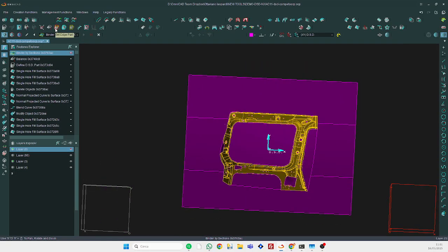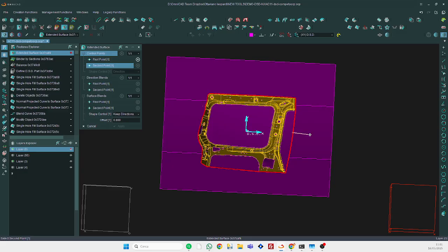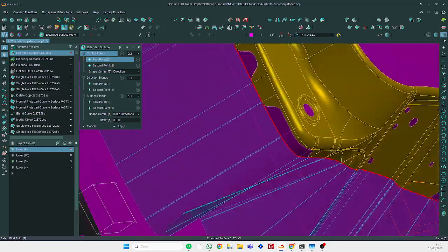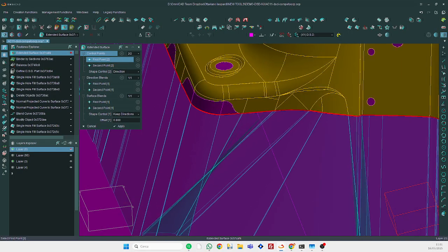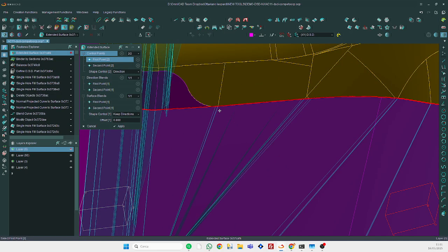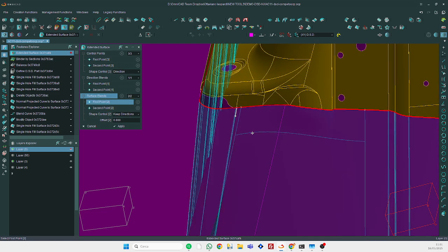Extend surface, next step is the extend surface. This is my profile from this to this. I have all the extension surface. Now we repair all intersection zones. For example, one is this, because the intersection is this, and you can either define the direction of the part and adjust the definition, or you can blend all the zones you need.